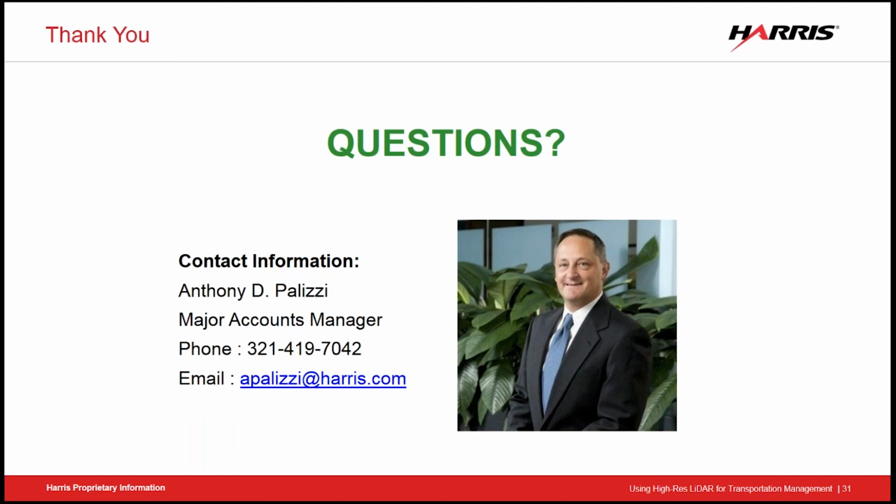Great. And then how has Geiger-mode LiDAR responded to high elevation collections through steep corridors? Okay, say that one more time, Jody. I didn't hear that too well. So how has Geiger-mode responded to high elevation collections through steep corridors like mountains? Oh, mountains, yeah. When we do our flight planning, obviously that's something we take into consideration, the elevation. So we'll adjust the flight plan for that.